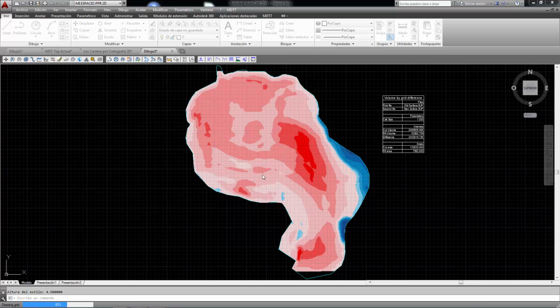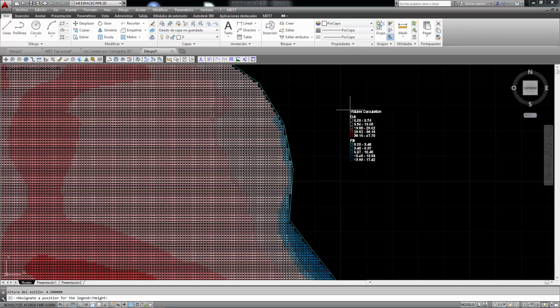also define our own cut and fill layer in the Cut and Fill layer, a new feature of DTM version 7.5. Moreover, we can define a palette of colors for the volume calculation intervals in accordance with the clearing and earthworks height, and then we accept.